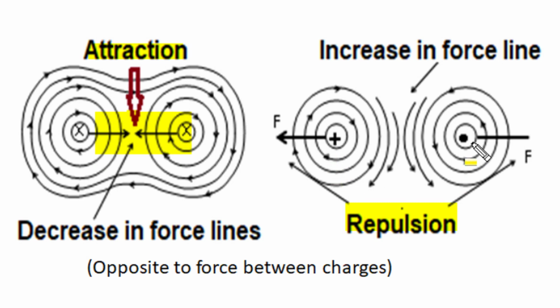Whereas when parallel conductors carry current in opposite direction, then for the inward current it is a clockwise circle, and for the outward current it is an anti-clockwise circle, and here force lines get added up, and this increase in force lines produces a field interaction such that it forces these conductors apart from each other, and there would be a repulsion force. So we can remember the magnetic force between two parallel currents is opposite to the electrostatic force of stationary charges, where identical charges repel each other, while identically directed currents attract each other, and opposite charges attract each other by electrostatic force, while opposite directions of current repel each other.